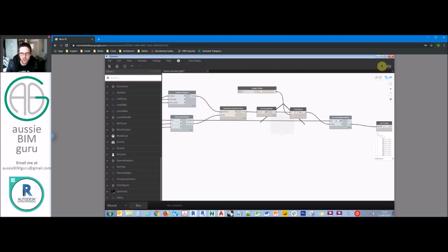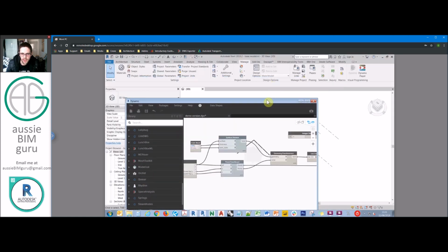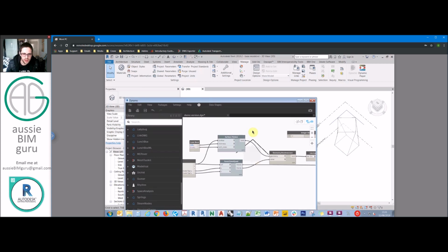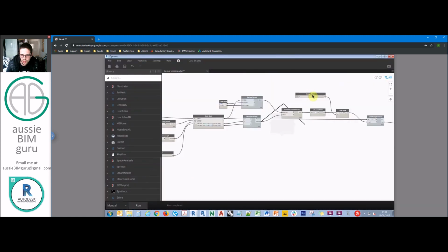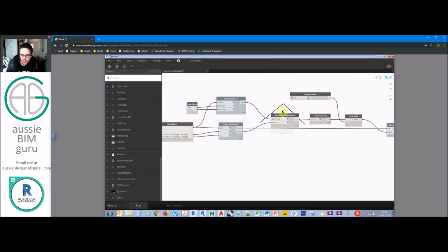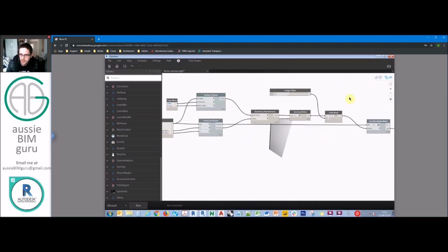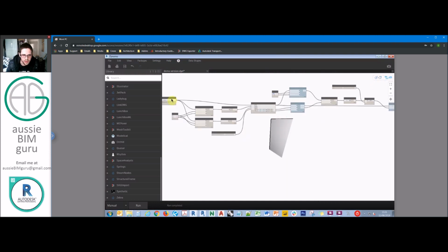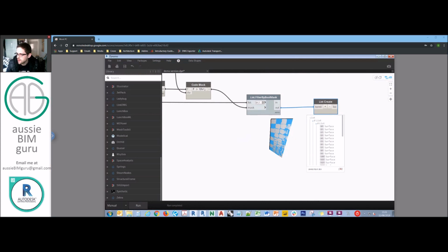But what we're going to do is just go back to our double curved surface. And that part of the workflow is very important. That one took quite a while for me to figure out, so I hope that helps you sort of take a shortcut. All right, we're just going to go back to our standard surface, and we're going to set our threshold back to 0. It has to fully intersect to be counted. Okay, so we're dealing with this surface again. And then what we can do is we can just turn off our preview. So now we're just dealing with our panels instead.